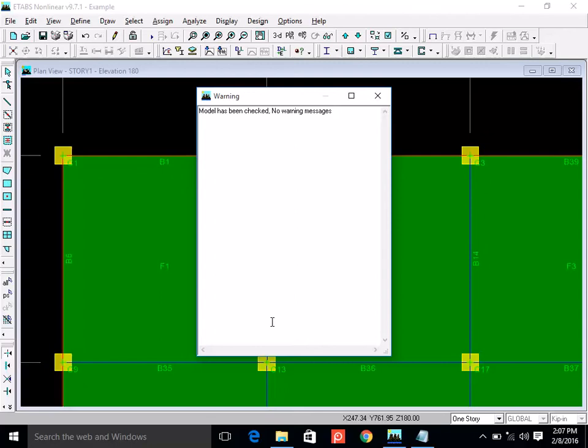This is B2 and right here is B42. Right? When my tolerance was 10 inches, the software provided me a warning. When my tolerance was 7 inches, the software did not provide me warning. Okay?